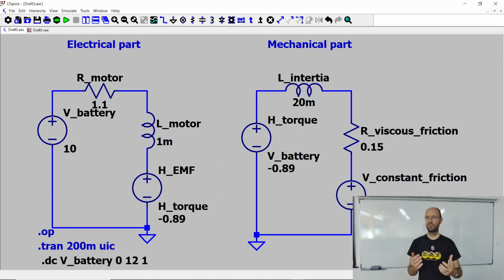And also if you have power electronic components that are switching fast, like silicon carbide, gallium nitride, MOSFET transistors, then they switch very fast. So you need to have very tiny time steps, and still if you want to simulate a motor, you have stuff that needs milliseconds or seconds to start to rotate to see some effect. So then you have nanosecond switching and maybe seconds while you're checking your control systems at the very same time. And then you need to have, of course, very many of these very tiny time steps.